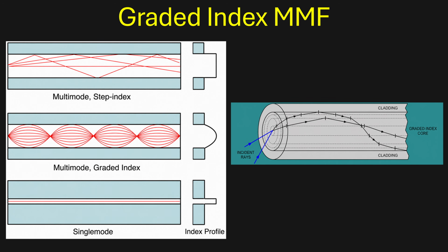The most effective mitigation of this is to use graded index multimode fibers, where the outer shells of the fiber have lower refractive index and allow the higher order modes to propagate at the same average speed as the first order. However, just like chromatic aberration in a lens, it does not work perfectly, and single mode is still superior, achieving faster baud rates and longer distances.